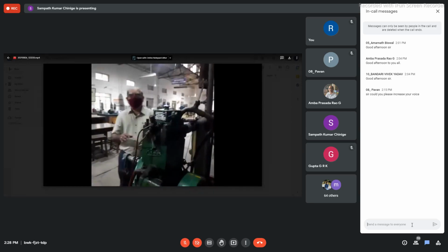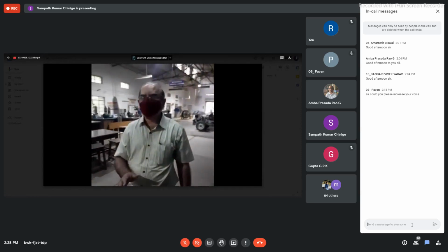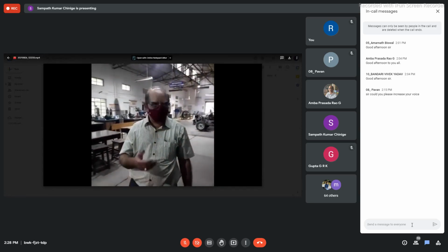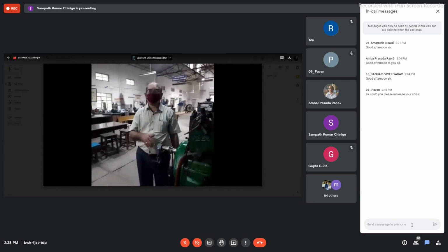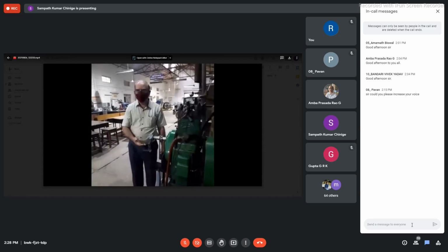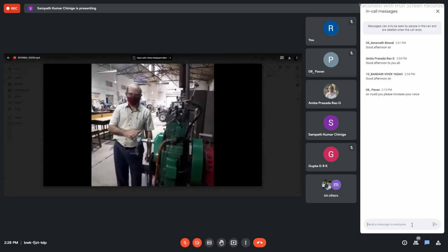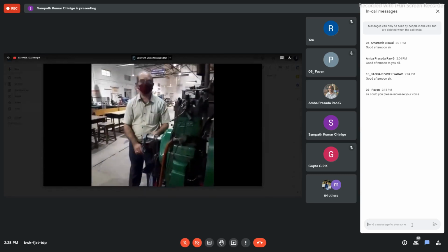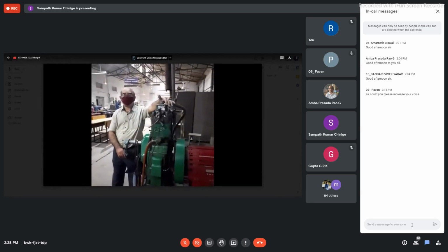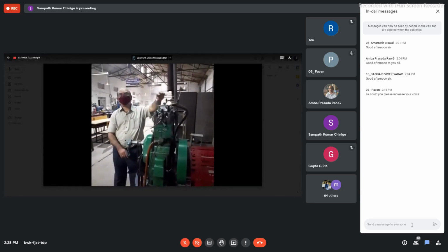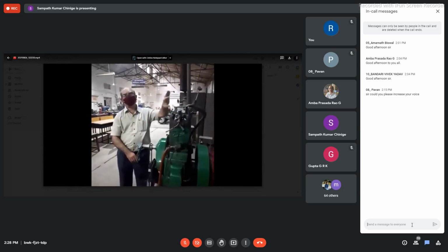The idea behind engaging and disengaging the decompression lever is easy cranking. By engaging the decompression lever, the exhaust gases of the previous cycle will escape when you are giving the initial momentum. It will allow the fresh charge to enter without any difficulty. Once the engine gains certain momentum, immediately disengage, by means of which the exhaust valve will be closed. So now it will give room for only the fresh charge to enter the engine cylinder for further development of power.